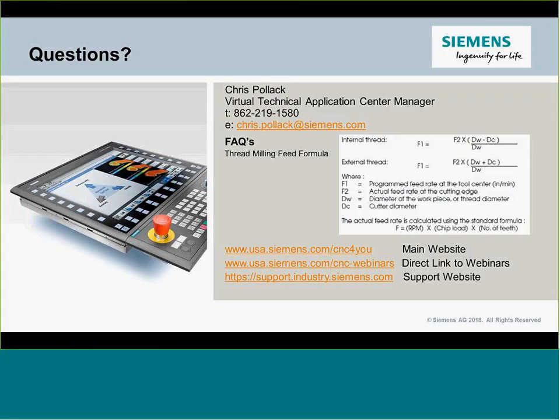Does adding an option like ShopMill and 3D require a service call? So generally, I would say no. Most of our options, those including, are pretty much set up right out of the box. So it's a matter of just turning on the license. You're going to want to refer to the machine OEM, whoever you purchased it from, to see how they like to handle doing it. But in a lot of cases, they'll just give you a simple procedure. You purchase the option, you have to put in a unique code into the machine, a couple of clicks, and the option is active.